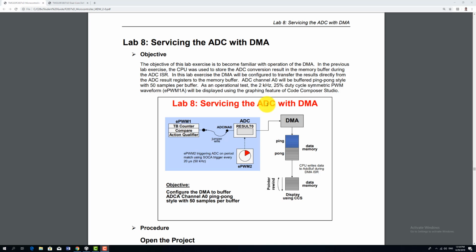When we say DMA, from the word alone, direct memory access, this is the method of transferring data, either sending or receiving, from the computer RAM to another part of the microcontroller system without using the CPU. In other words, we will be bypassing the process involved in the CPU. DMA can save processing time, and it is more efficient and faster in transferring data.